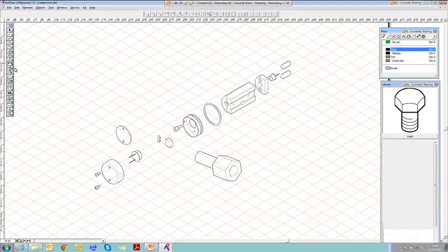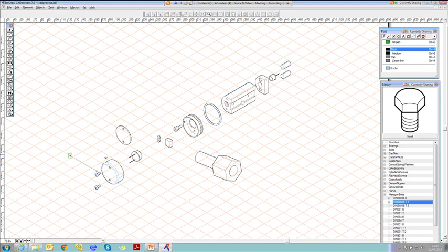You could then go through and add some callouts onto your model. So you might add some callouts like so. You can work through this and position these. Again, these will snap to the grid that we've got in the background. So you might position your callouts on your model to make it nice and tidy and easy for someone to understand. But the speed comes from the fact that we're using our 3D CAD data. So we've utilised our 3D CAD data within this system.